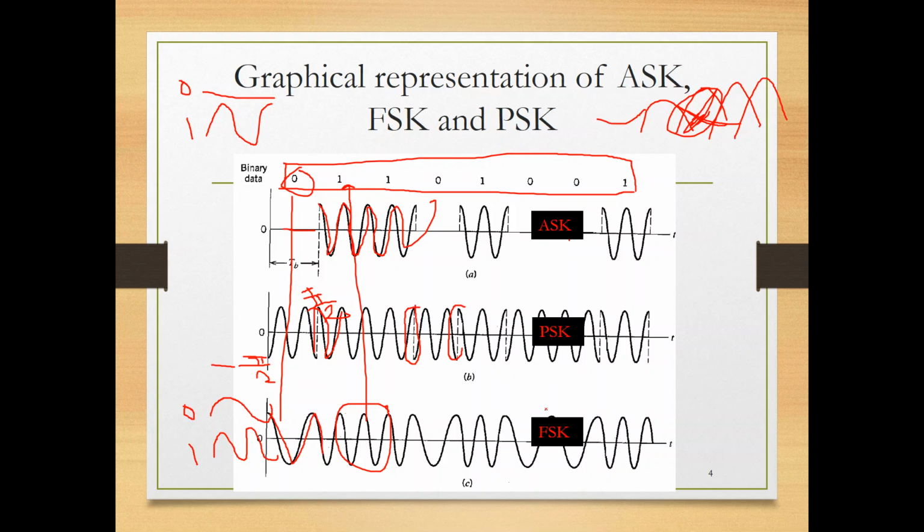This problem is usually faced by broadcasting companies. Like you are a reporter working in Al Jazeera or working with TRT World, and they hire engineers like you to adjust the parameters of the transmitter that communicates with the satellite. For example, when there is noise, when there is degradation, the picture of the reporter is not showing very good, they reduce the modulation, they change the modulation, play with these parameters just to make sure that the connection is always reliable.